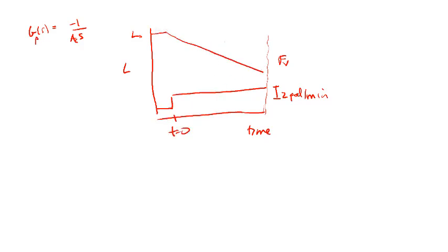So this is going to be linear. Now I'm going to leave it up to you. In general, this is going to be linear until the tank empties out, because if the outlet flow is 2 gallons higher than the inlet flow, eventually the tank is going to empty, and anything that comes into the tank is automatically going to exit, so it'll stay empty. So this slope should be linear, and I'm going to ask you, what is the slope? Use your understanding of the model to figure out what the slope is for this process.